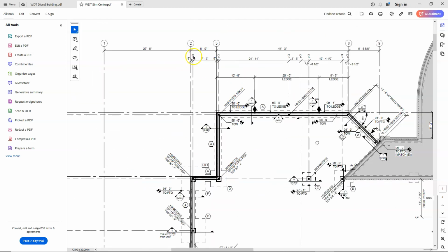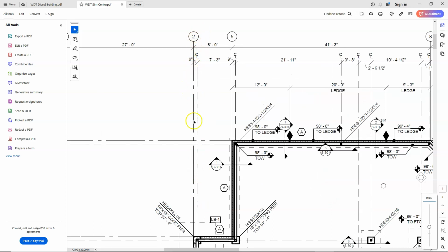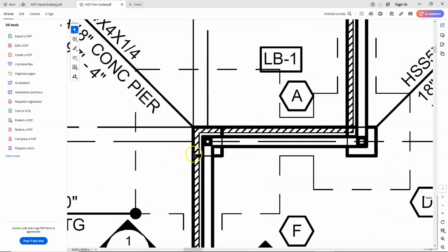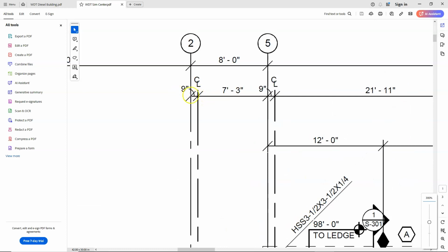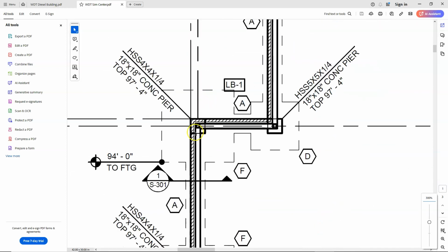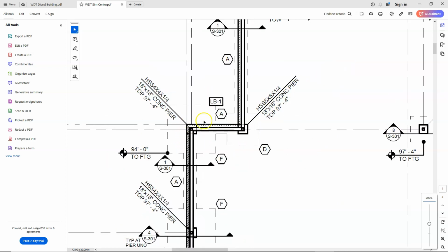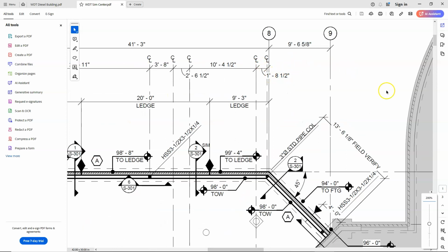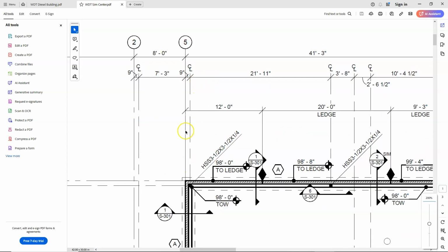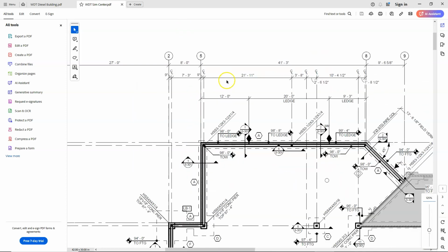The building ones, however, are the grid lines are going to line directly up with, again, the edge of the masonry, which we can assume also is going to be the edge of the foundation. But then there's also another sort of line. It's not really a grid line, it's just sort of a reference line 9 inches away from the grid line, and that is where we're going to be placing the center of the steel columns. So this building does have steel columns in it and masonry, and so they just had to use this slightly unique technique of defining the outside face of the concrete with the grid lines and then a reference line just showing where those columns go.